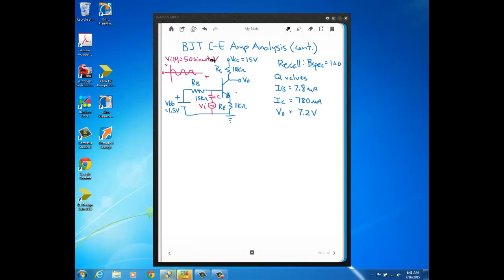And in order to do that, we have the transistor that has the ability to amplify, as we discussed in a previous video, and we're supplying the DC energy to power that transistor to amplify this AC signal. So the big picture is we're going to get a bigger amplitude AC signal here at V_out compared to what we have as our V_in, and we don't get that amplification of the AC signal for nothing. The cost is the DC energy that we supply to the transistor circuit to power the transistor.